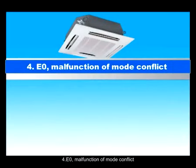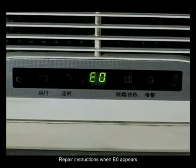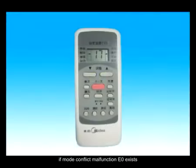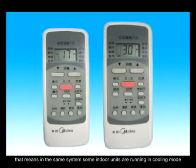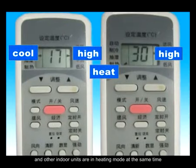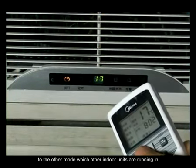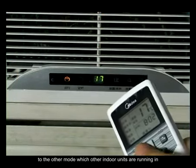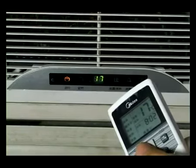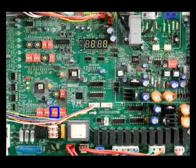4. E0, malfunction of mode conflict. Repair instructions when E0 appears. If mode conflict malfunction E0 exists, that means in the same system some indoor units are running in cooling mode and other indoor units are in heating mode at the same time. The malfunction can be solved by changing one running mode to the mode which other indoor units are running in. We can use the outdoor mode lock function to lock the indoor unit running mode. That will help the customers operate more conveniently.